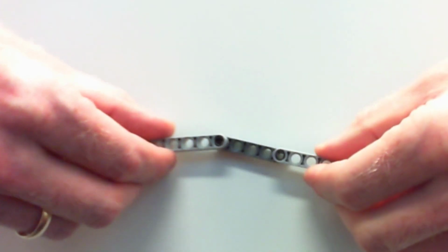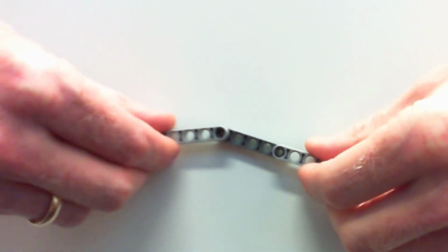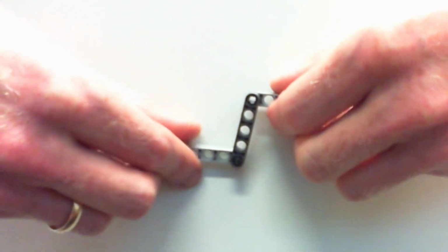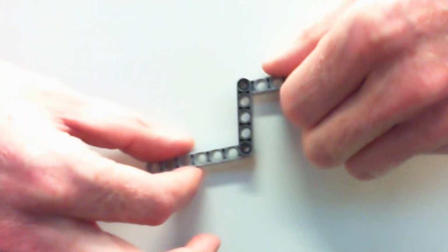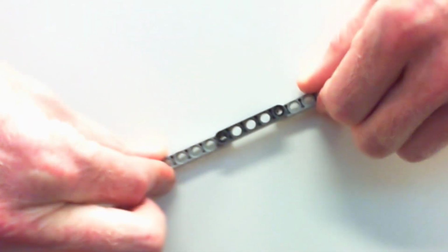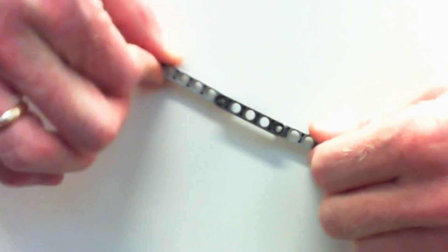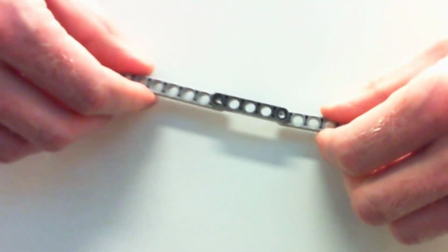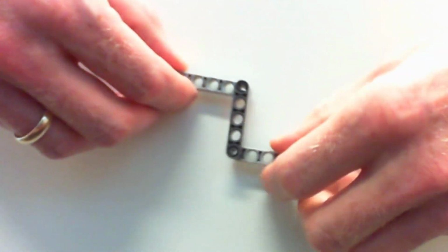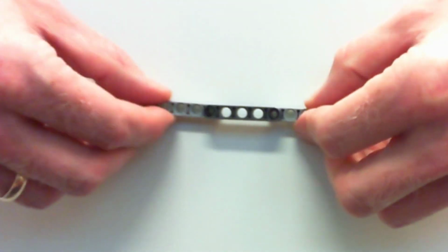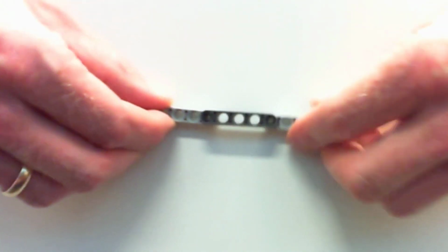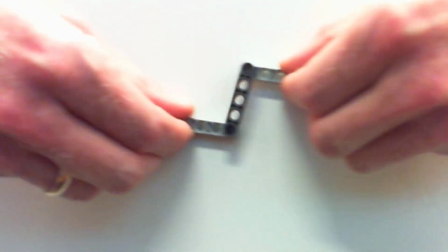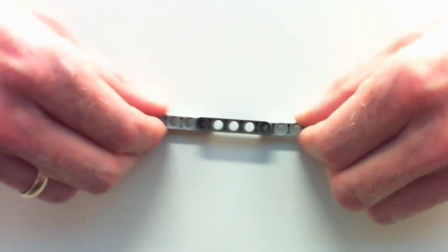Okay, we're assuming no resistance to bending, but it's always going to be basically in line with the connection points on the end. It's going to be the same thing for a weightless link. Okay, so this piece in the middle here, the darker gray piece, I'm assuming is my weightless link. And so however I pull on these two ends, you can see that that weightless link is going to fall in line with that tension. Okay, so I'm showing it here in tension. Now a weightless link can also hold compression. If I get these forces in line, I'm actually pushing on either side toward the middle here, I can create a compression force as long as I keep that in line.